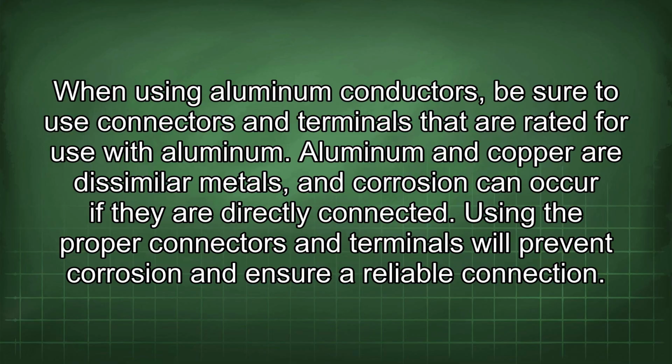Aluminum and copper are dissimilar metals, and corrosion can occur if they are directly connected. Using the proper connectors and terminals will prevent corrosion and ensure a reliable connection.